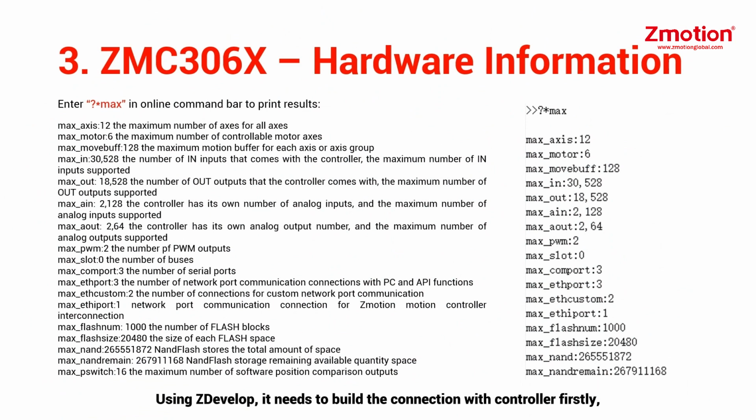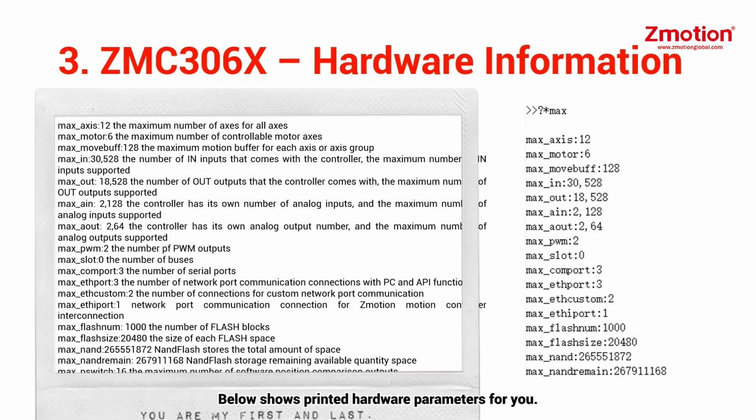Using ZDevelop, you need to build the connection with the controller firstly, then enter $max in the online command bar. Below shows the printed hardware parameters for you.